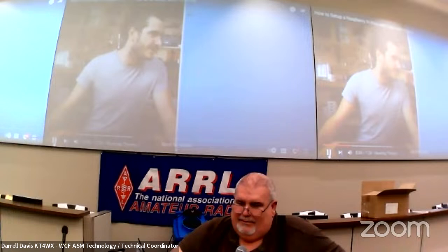Right, let's run Thonny. Time to plug in the Pico, and my Pico has pins on it. It's okay if yours doesn't. It doesn't make a difference for now. You can buy it with and without headers. Connect it to your computer through the USB cable. Go to Run and select Interpreter, and make sure that you select MicroPython and Raspberry Pi Pico. It's also a good idea to install or update the firmware first.